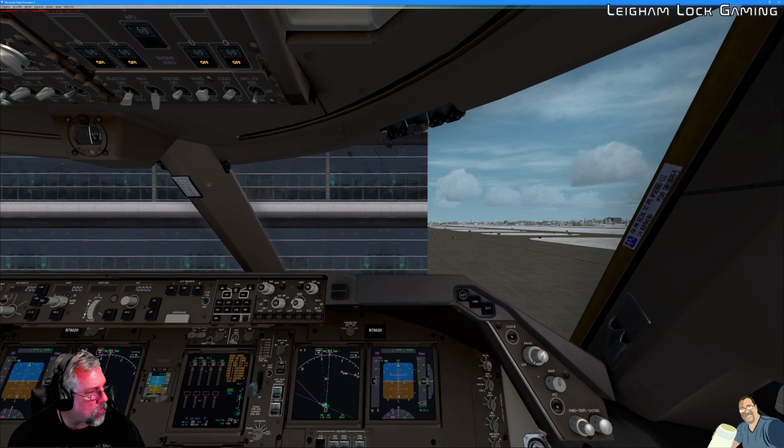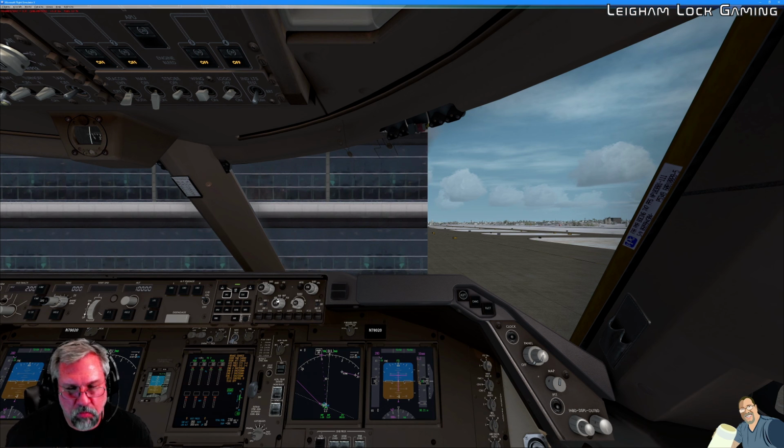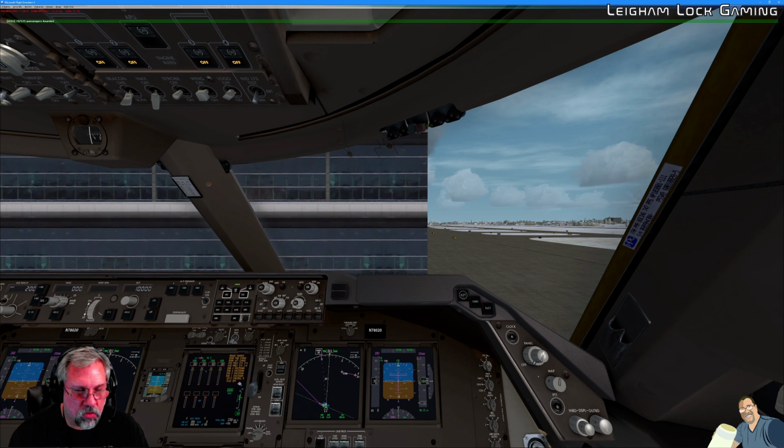Now here's where we get into the EFIS control. Recall that the EFIS control on the right hand side, so that's the first officer's EFIS panel, is mostly disabled. So one of the checks on here, if we were to interact with this console, as I've already shown, some of this stuff might work, but most of it is disabled or not going to work. If you had to make a change to check a particular setting, you would have to turn off that right CDU so that the EFIS control is restored back to this right panel.